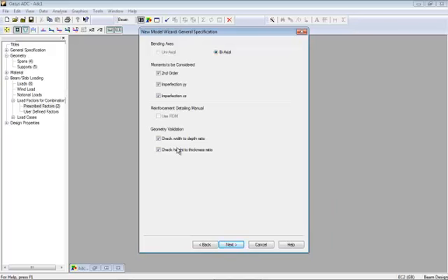Again, also additional checks for validation. Sometimes you'll see if you've specified a column which is too short, columns have to be a minimum length, and so you might get an error there. Likewise, height to thickness ratio might make it too long. If you're confident, you can switch these checks off, but they are in your hands.